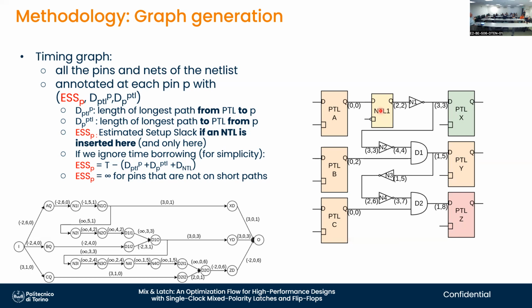So that actually was intuitively reasonable. We thought that incremental place and route could work in this case because we are not changing the circuit too much. But in practice, it turned out to be false. So incremental place and route works only with smaller changes. It is meant to work when somebody changes from +1 to +2 or something like that. Not when you take maybe 1/3 of the flops and convert them into pairs of latches.